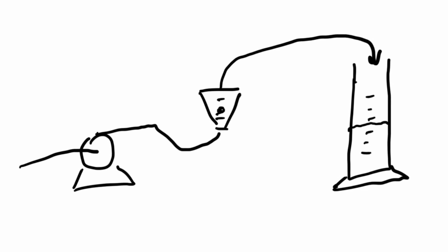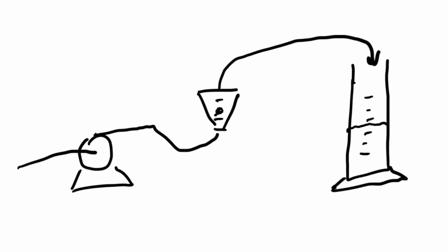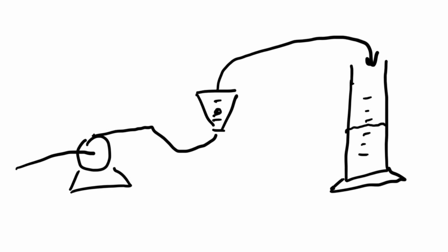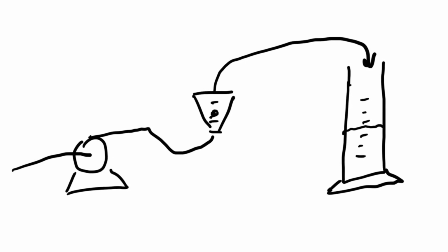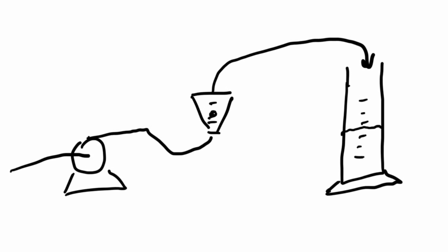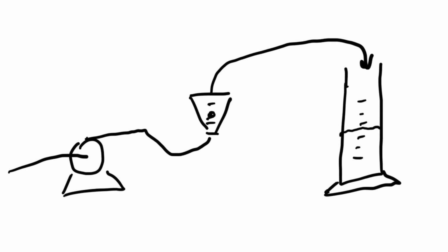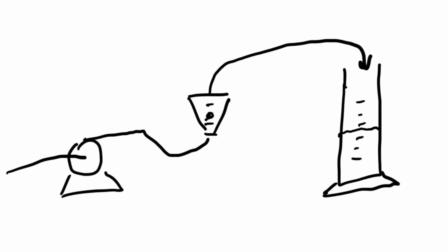The problem statement says, before a rotometer can be used to measure an unknown flow rate, a calibration curve of flow rate versus rotometer reading must be prepared. A calibration technique for liquids is illustrated below. A flow rate is set by adjusting the pump speed. The rotometer reading is recorded, and the effluent from the rotometer is collected in a graduated cylinder for a timed interval. The procedure is carried out twice for each of several pump settings.